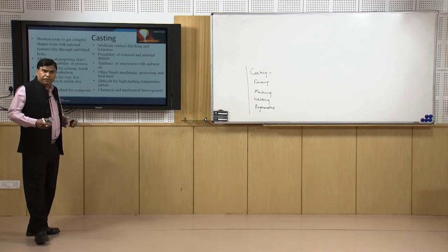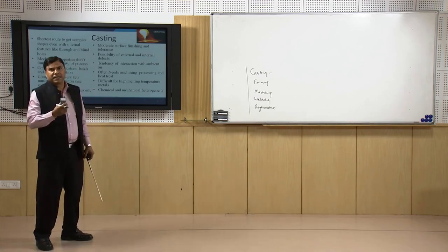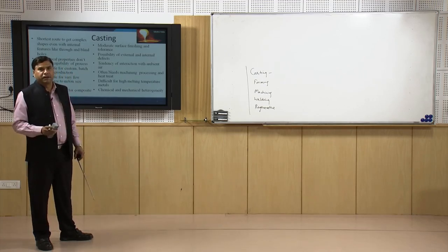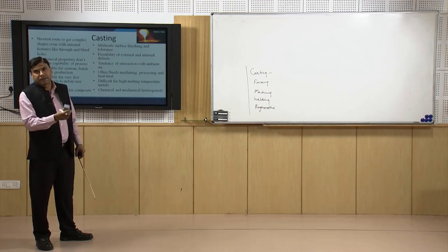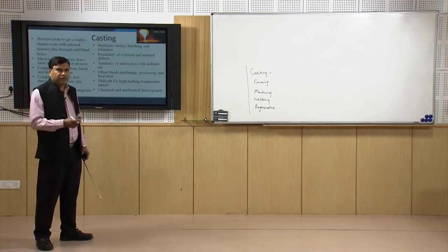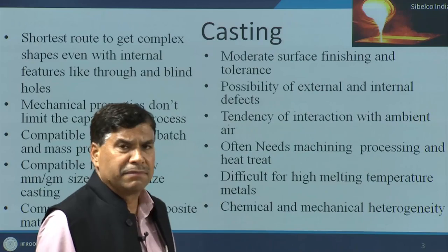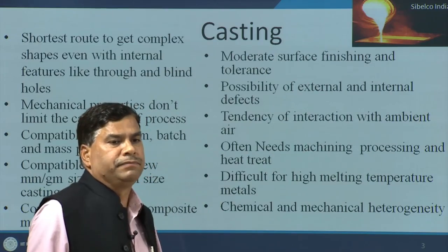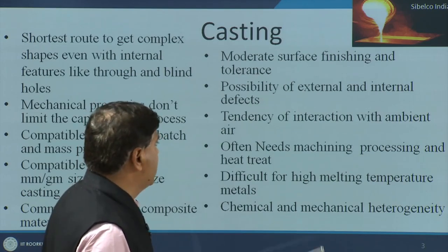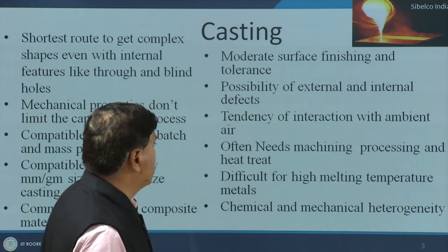We know that the molten metal will be solidifying. So, if the gases get trapped or impurities are passed along with the molten metal into the mold, then they will be present in the form of porosity or inclusions, which will be leading to the internal defects. At the same time the formation of cracks due to the high residual tensile stresses can lead to the development of cracks at the surface of the castings.